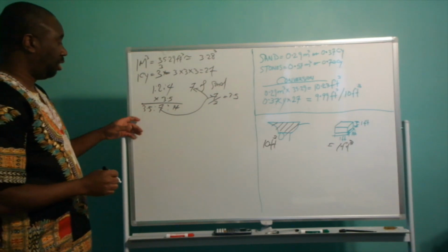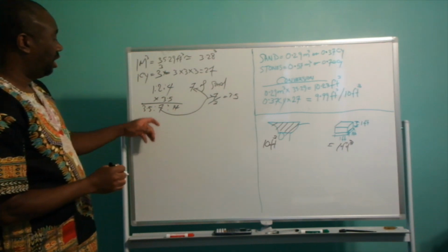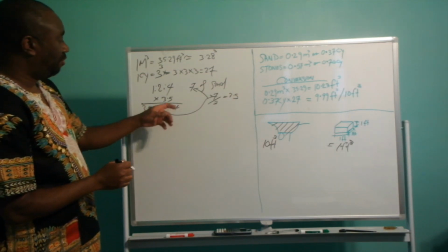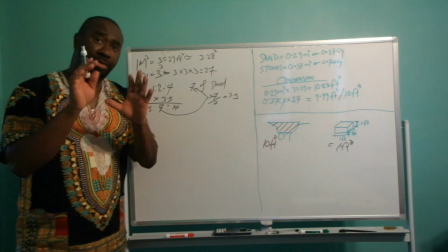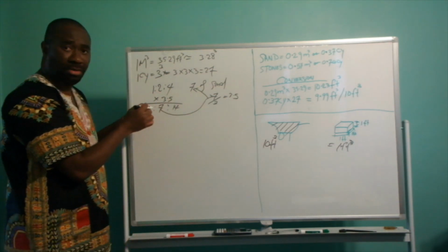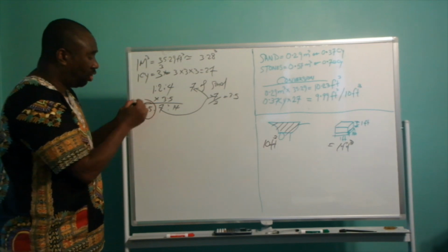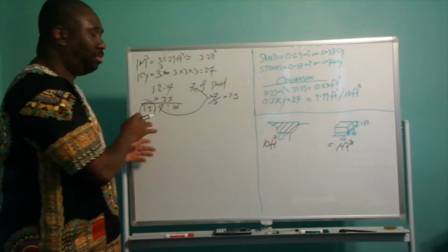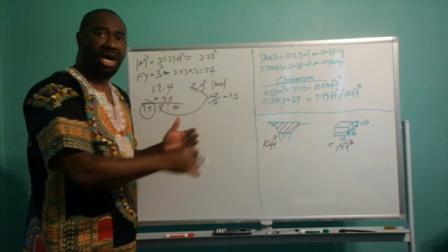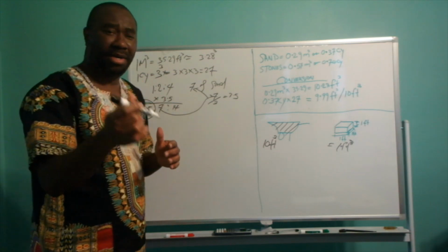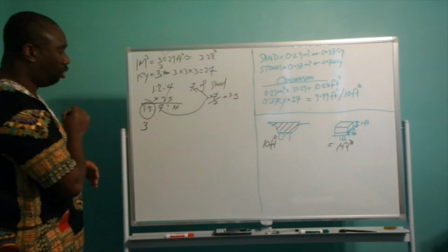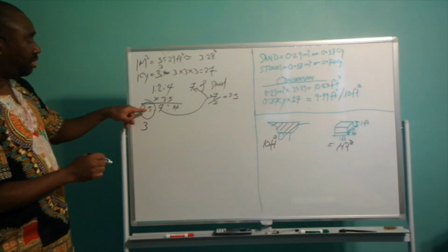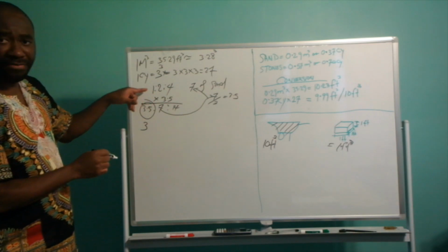So your mix proportion is going to be 3.5 barrels of cement, 7 barrels of sand, and 14 barrels of stone. But the difficulty I'm having with this mix proportion is that you do not want to work with 0.5 or decimals, because no one is going to have the time to measure out half of a barrel of cement, right? And more often than not, that is not going to do. You're going to only quantify 3 barrels of cement, which is going to rob your mix of half a barrel of cement.